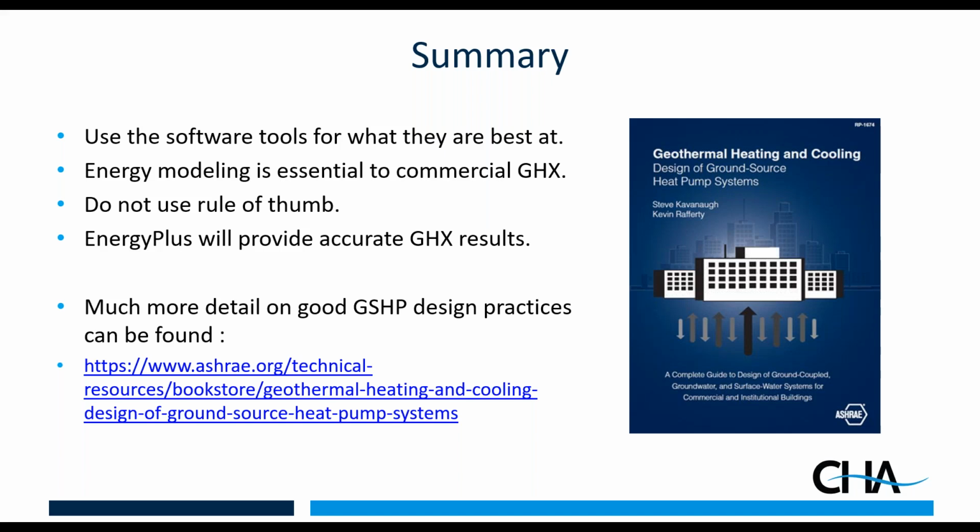The energy modeling is such an essential part to doing the commercial ground heat exchangers correctly, and capturing all of the good energy efficiency measures that are being put into these buildings, especially when you talk about energy recovery and things that are driving the loads of the building one way or another. Please don't use rules of thumb. Energy Plus does provide really good, accurate ground heat exchanger results, so you can use it with confidence to test out different setups and different control schemes, and you'll get a good data set from that.